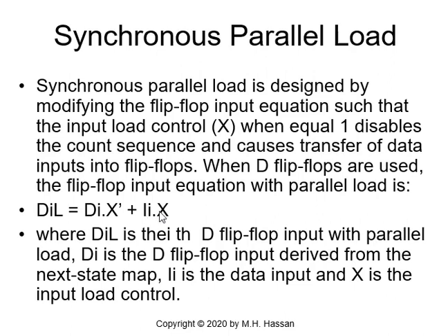So this Boolean function, this logical function, is very simple logic used here with a control signal X. If X is 0, I have a normal counter. If X is 1, I am uploading data synchronously to the counter. So with one clock pulse, all the data will be loaded synchronously to the counter.